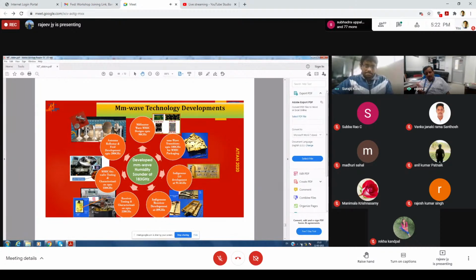I'll give you one example. One of our earlier bands, which was meant for radar, is now being used for wireless LAN. Even though the wireless LAN has maybe a 3 to 4 dB gain, and in the direction of a satellite it will be very less, and the power is also very small, it can definitely interfere, even with the cross-polarization signal. The noise floor of the system becomes very large and gets affected. So these are things we have to solve earlier.